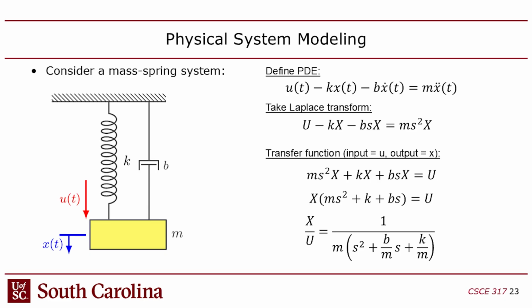If you go slower, no problem. But the faster you go, the more friction acts against you. That's why this B, which is the dampening factor, is multiplied by x dot, which is velocity, right? Make sense? So anyway, you figure that out and you get a new transfer function. And this one, I believe, is this one stable? I forget.